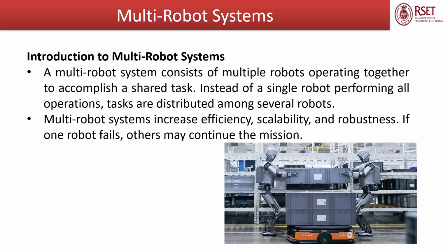Motion planning generates a desired trajectory. Control ensures that the robot follows it accurately. If control is poor, the robot may drift, overshoot, oscillate, or become unstable. If planning is poor, the controller may struggle, motion may be jerky, and physical constraints may be violated. So robust navigation requires both strong planning and strong control.